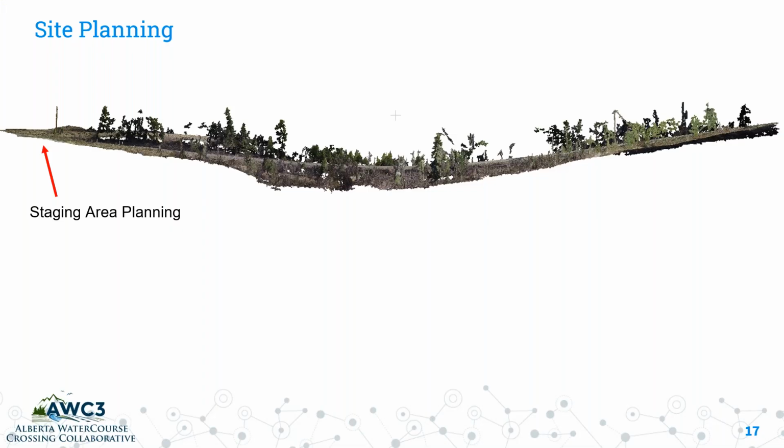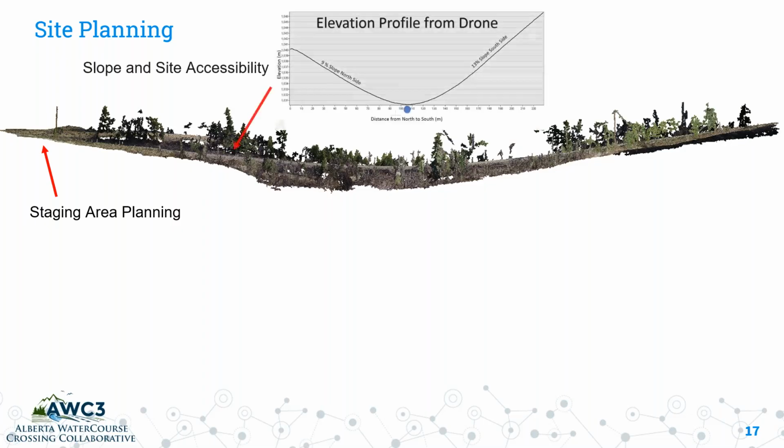Well, if we go back to that original video, what we see here is essentially the oblique angle of that road. And what I see here is, okay, we captured more area than the actual roadway watercourse crossing itself, so that we would have a better idea of what we're doing. So I could use the drone imagery here to extract the elevation profile.